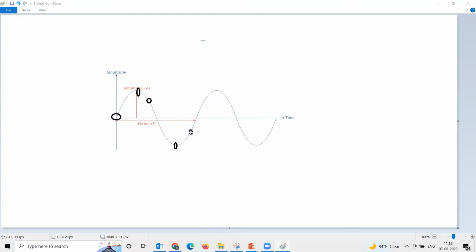You should not say that your calculation is wrong because the actual fault current is different. When the actual fault current is less than your calculated short circuit current, then it is perfect, because the instant at which the fault has occurred might be different. The pre-fault voltage might be different, the pre-fault loading condition might be different. The fault may not have occurred without impedance, it may occur with fault impedance, and so forth.